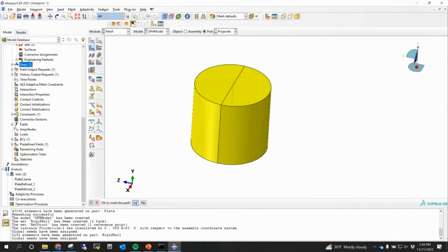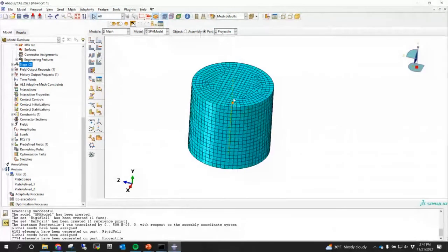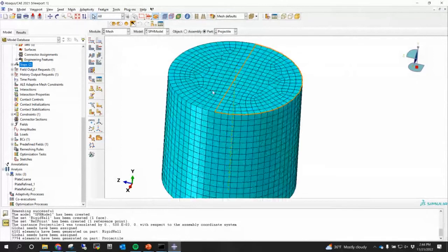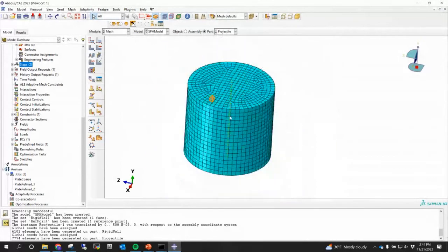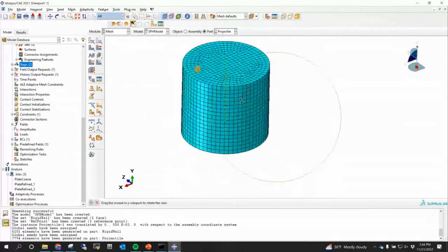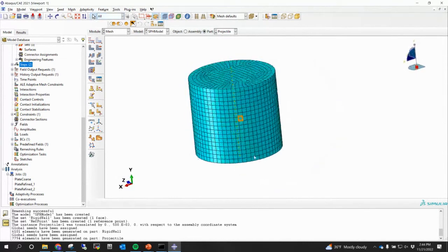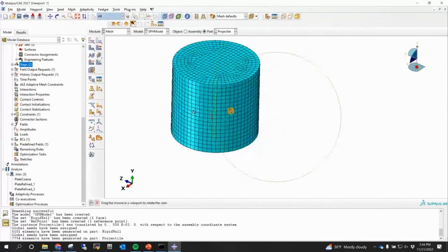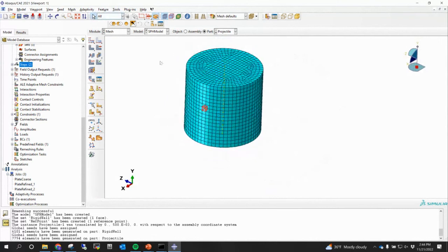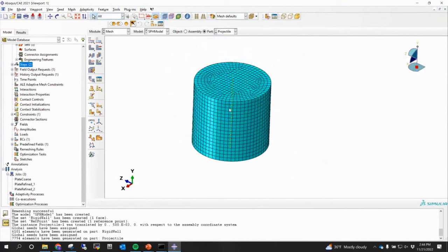And then I can go ahead and mesh. All right. It's kind of homogeneous. There are some elements that could be improved, but this mesh is going to work. It's very structured along the z-axis, so the spacement between particles is okay. I'm not going to go into much detail there. I just want to show this could be improved, but I just want to show the capability here and how this could work.